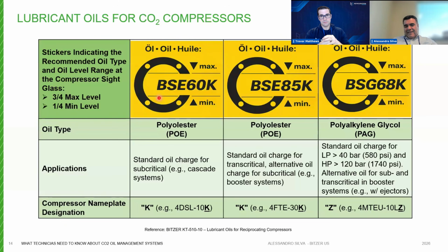This will affect the oil lubrication properties, and of course, this is not recommended. We may not create a chemical reaction, but we for sure will change the properties of the oil, and this probably will not be good for complying with all the lubrication properties we expect. So our recommendation is never, never mix different types of oils.